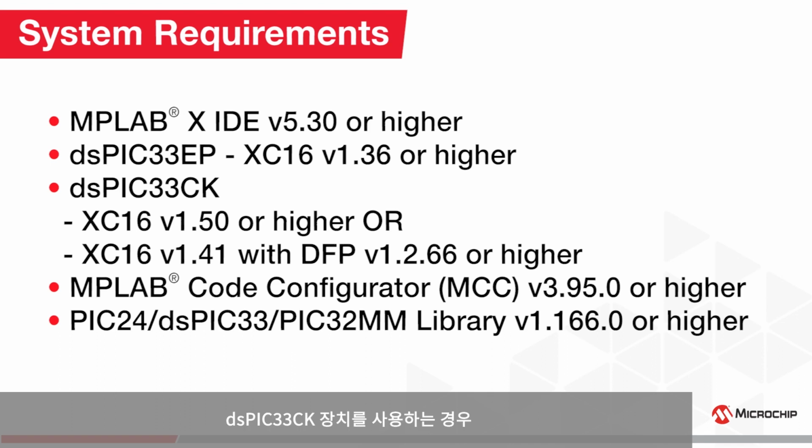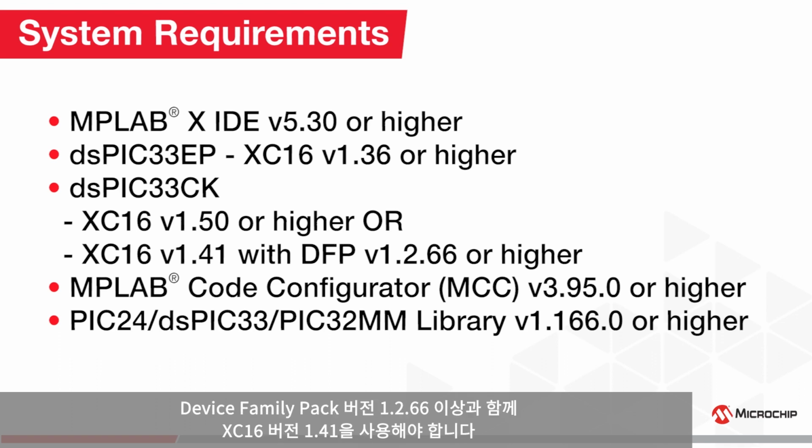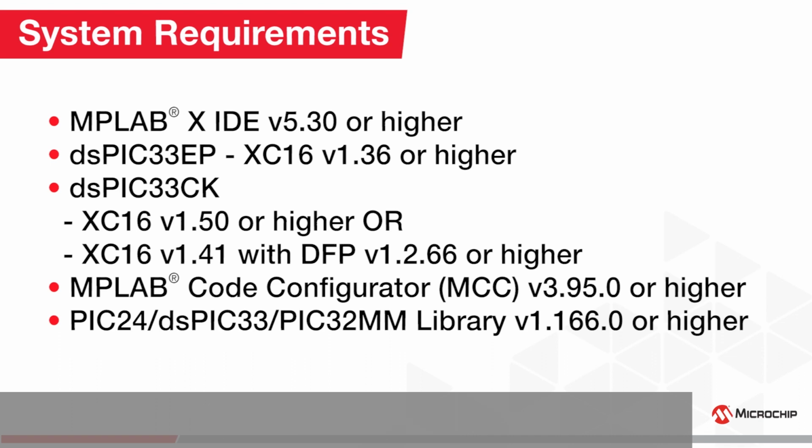If you're using a dsPIC33 CK device, then you should either use XC16 version 1.50 or later, or you should use XC16 version 1.41 with a device family pack, version 1.2.66 or later. The firmware itself has been tested with XC16 version 1.41.